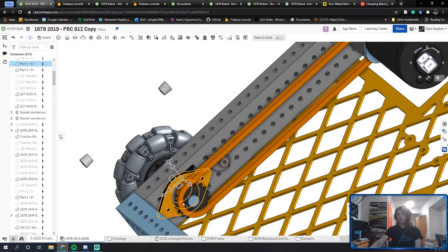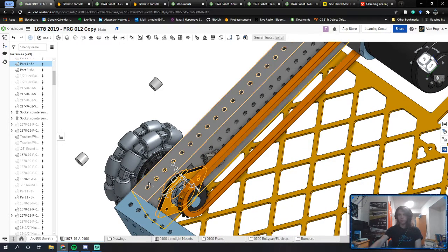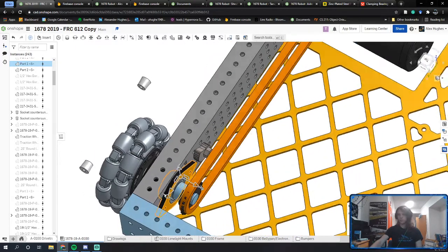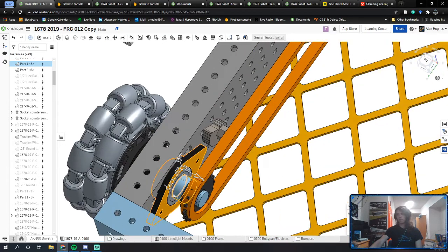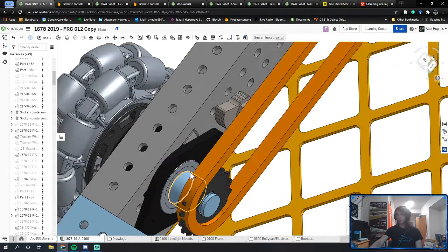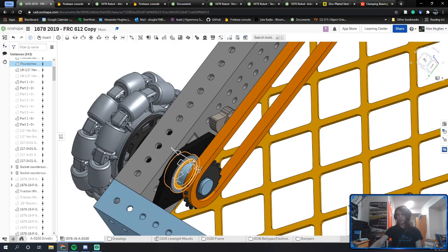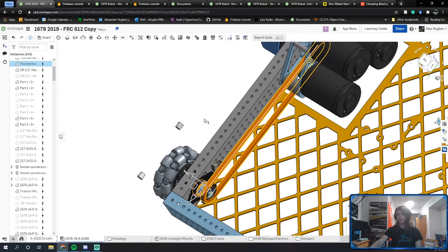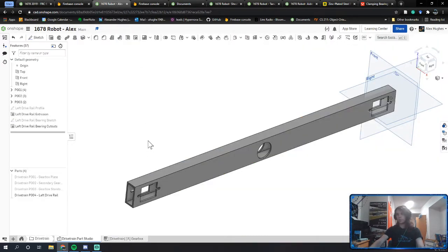These, on the other hand, don't have that issue because they're being mounted through the aluminum tube. We'll see how they do that here in a second. But these are just a different form of bearing block. As you see, they still hold the bearings right here, and they're adjustable. That's kind of the key thing about these. They can be pushed left or right based on how much the chain stretches over time, which is very important. You always need to make sure wheels are tensioned.